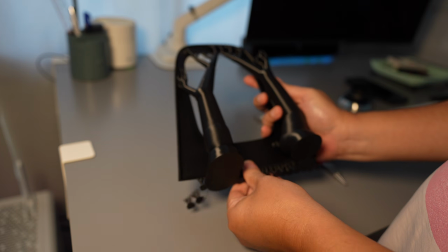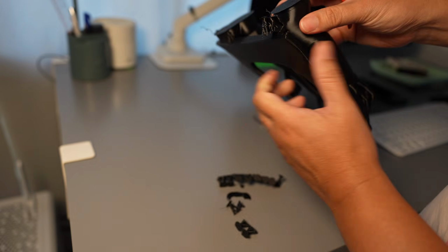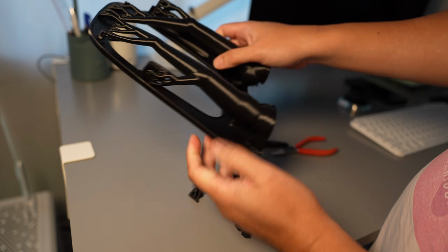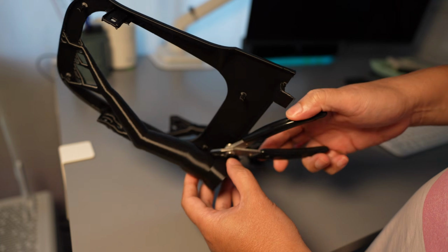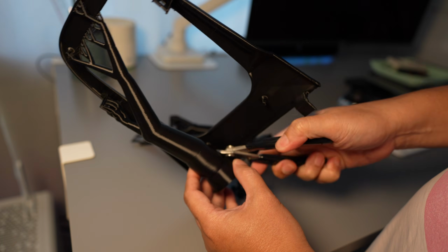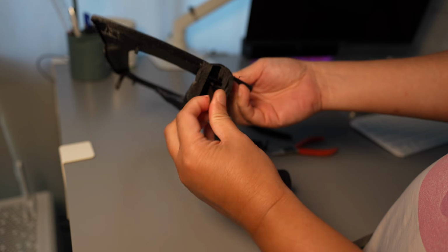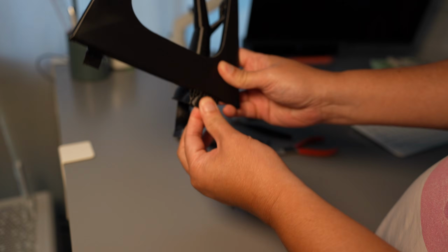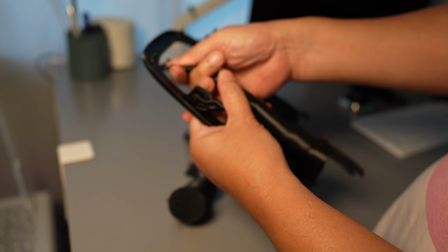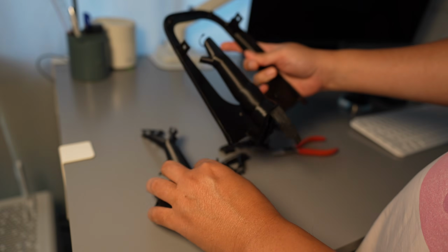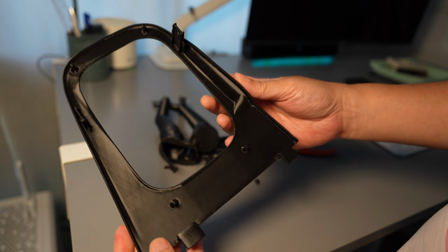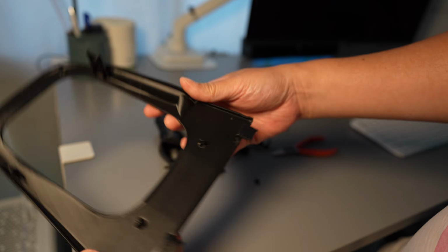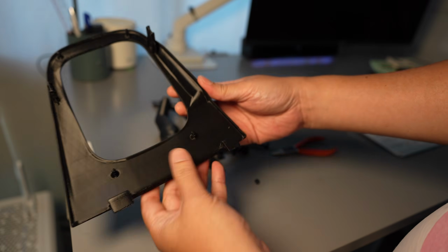When you dry your filament, whether ABS, ASA, or PLA, support removal becomes much easier. I start by using a side cutter to separate the supports at their weak points, and this way when I pull out the larger tree supports, they won't break the clips or stand-offs. But if your filament isn't dry, support removal becomes more difficult and you risk breaking clips.